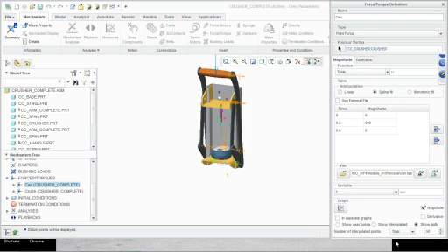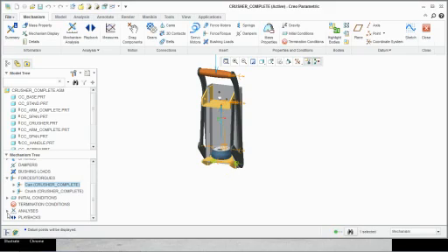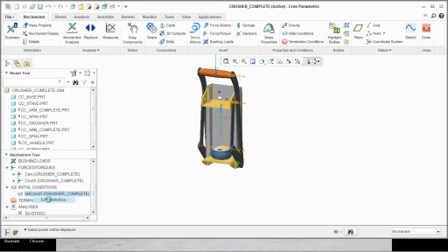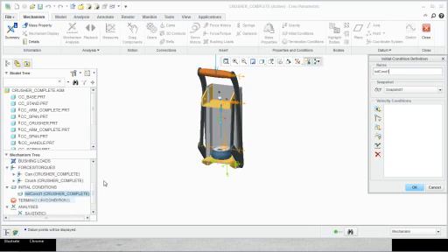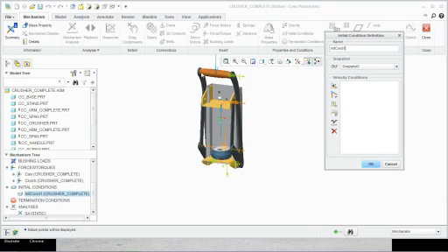So once that's done, we can see that there is an initial condition right here. Initial condition is, hey, I want you to always start the analysis at this position. And then I can say, I want to define an initial velocity to a point. I want to define a motion axis velocity to a point. I want to define an angular velocity, tangential slot velocity, or once you define all this, you can evaluate all the velocity conditions. So you can do that too.